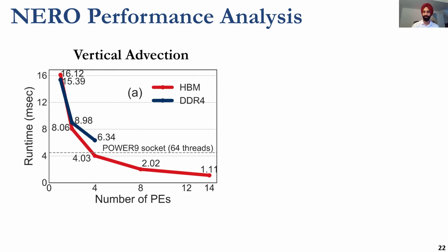We perform in-depth scalability analysis where we scale the number of processing elements and analyze the change in execution time. For the DDR4 based design, we can accommodate only 4 processing elements on the 9V3 card, while for the HBM based design, we were able to fit 14 processing elements before exhausting the onboard resources. We make 4 observations from the figure.